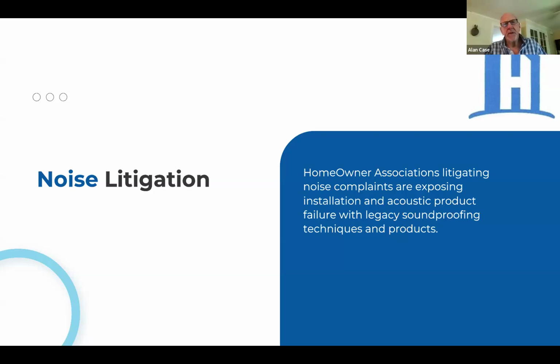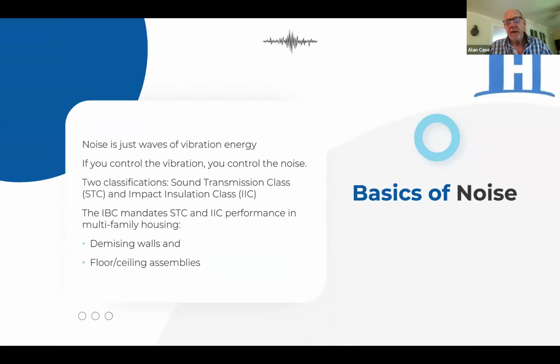Well, it's a tragedy because we have 3 or 4 fairly big projects in Boston that are going through this right now, and they don't like to talk about it. Once it's discovered, the homeowners are hiring law firms, and there's a couple of law firms now that have caught on to the developers that have these problems, and they're pursuing the HOAs, and then they're bringing in a field testing company for acoustics, and they're showing that they most often squeak by on the STC on the floor ceilings, but they're failing miserably in the IIC on the impact noise, which is what drives everybody nuts.